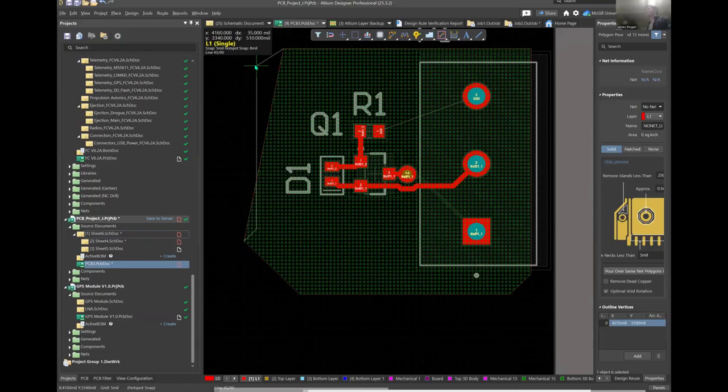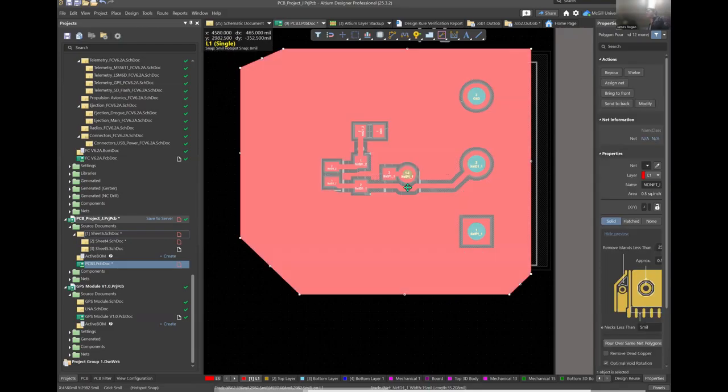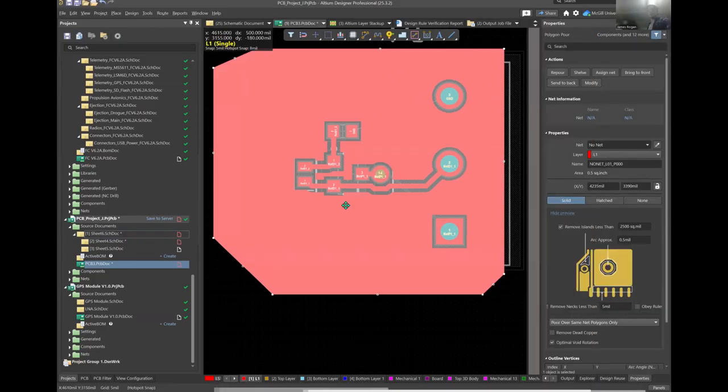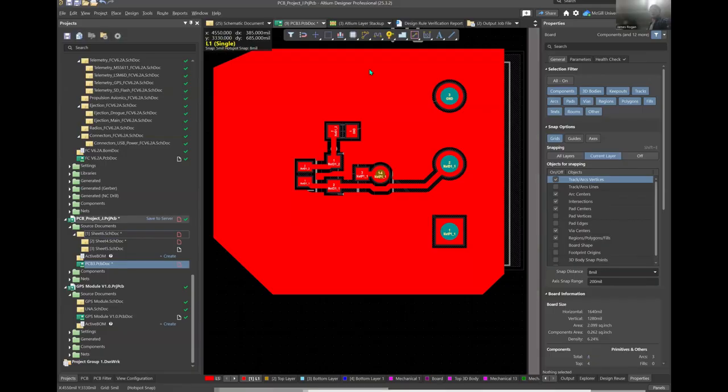There's a lot of tools online, documentation for how to use polygons. But yeah, so you can see it gives you something like this. Right now, there's no nets connected to it. In real life, this is a solid pour of copper. So all of this lighter green stuff here is copper. This darker green stuff is just solder mask with no copper underneath it.